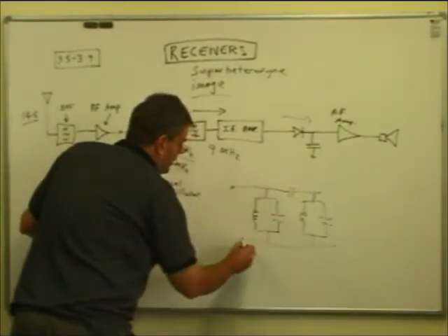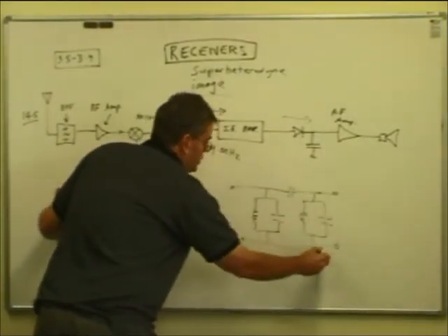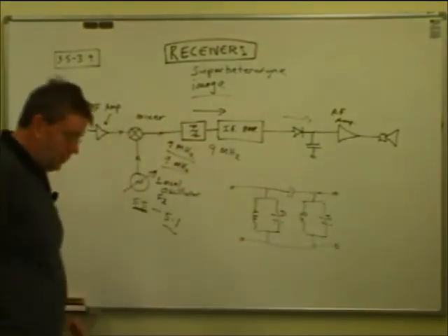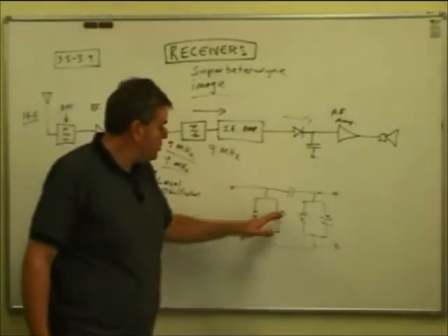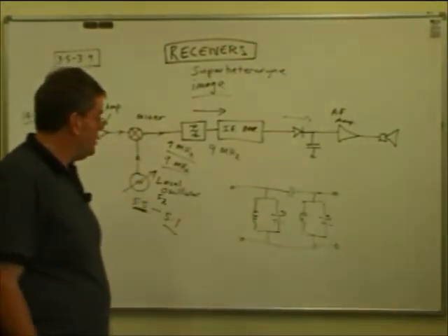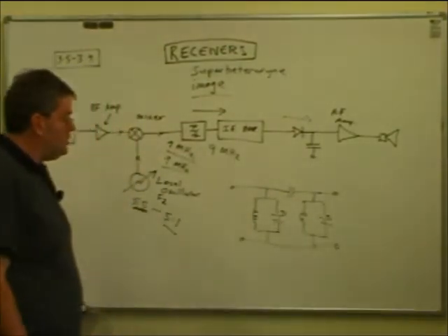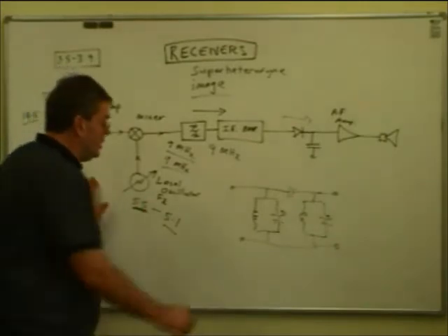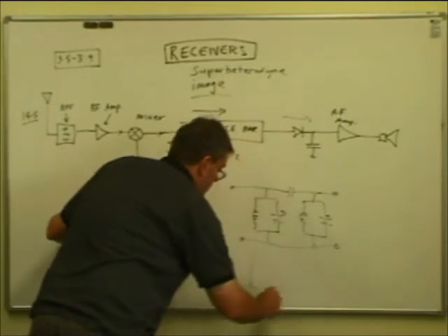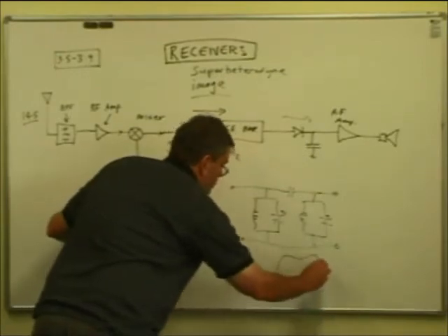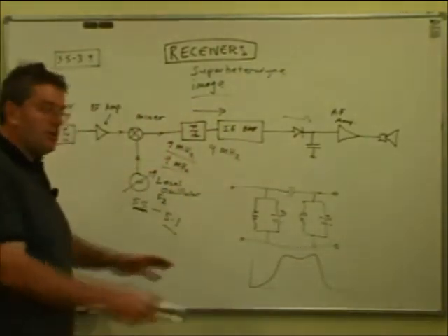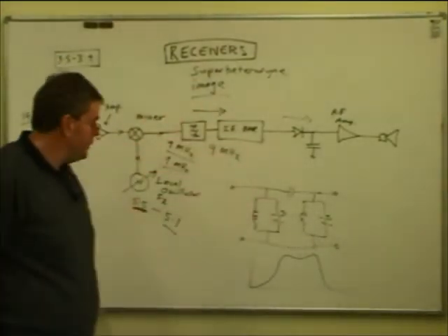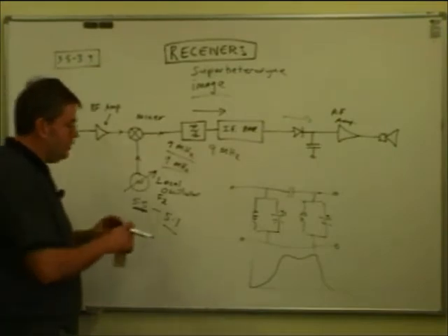This kind of arrangement with these two tuned circuits, tuned in a particular way and coupled together with a capacitor like this, will quite cheaply pass the particular band of frequency we want. The response curve will be something like this, generally a sort of double-humped arrangement like that, and the sides aren't as steep as a crystal filter we'd use there. They tend to be rolled off a bit. But that's good enough most of the time for the job we want to do.